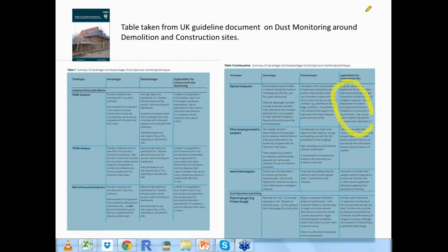That real-time measurement is a key advantage because it allows site managers and environmental managers to react quickly to short-lived particulate emissions. One typical example is to use the instrument measurement to trigger a sprinkler in order to suppress dust emissions from a road.